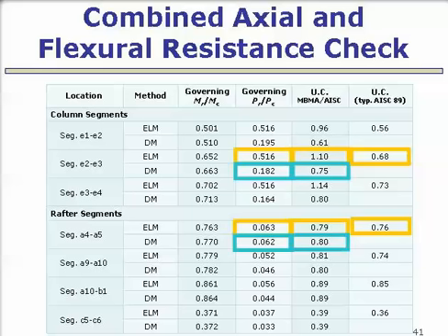If we look at the rafters, our axial strength ratio there is pretty much the same, either effective length method or direct analysis method, because both are pretty much non-sway checks there. We put that together with the moment ratios and get essentially the same answer. It's just a shade higher in the direct analysis method. Why?